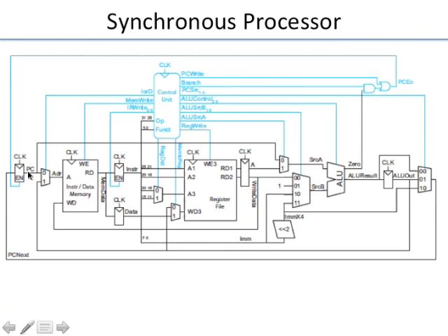And these blocks are what are called flip-flops or sequencing elements, and then you have some computation happening here. This is a register file. This is the ALU, and then you store the data, and so on. So you see there are two kinds of circuit design elements here. One is the logic gate, which forms the multiplexers, adders, subtractors, and other things.